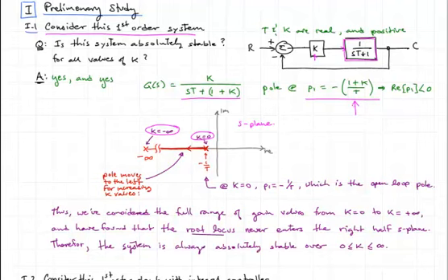If you have K equal to 0, there is no way for the reference signal to get in. However, it's still true that our response c(t) is due to a system 1 over sT plus 1, and thus, if there was an initial condition on that system, we would see it decay according to a time constant of capital T, or a pole of minus 1 over T right here.